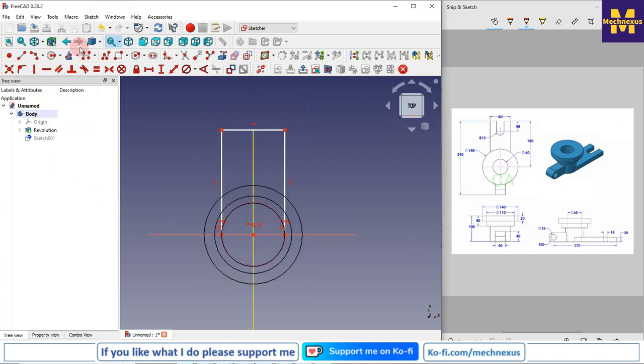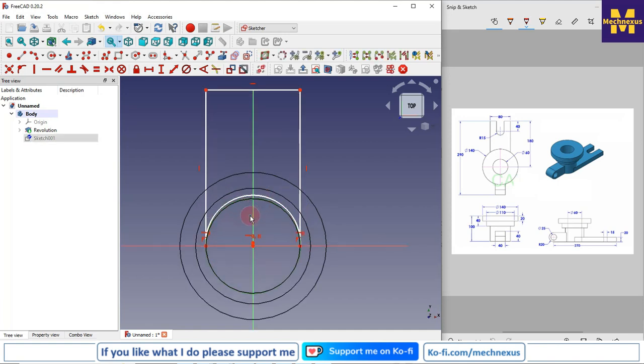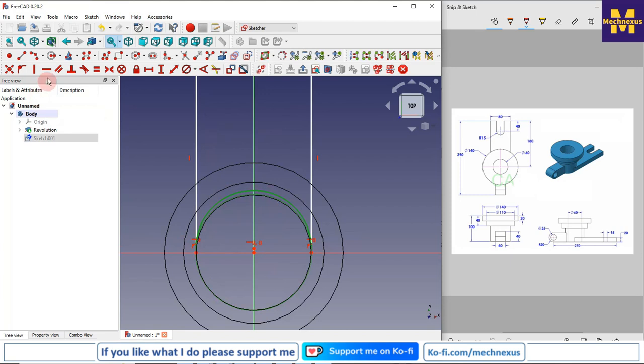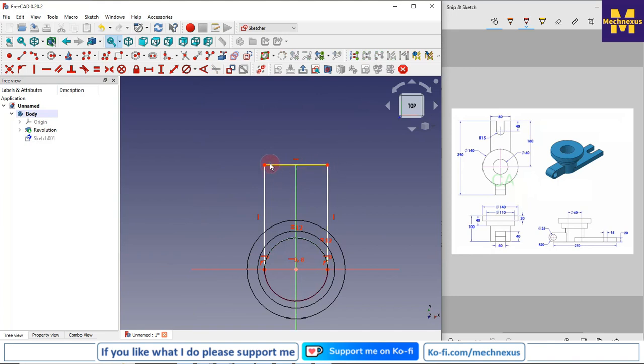Now I will create a 3-point arc. Select this point and this point, and now I will select this and make it equal, and now I will make it symmetric.